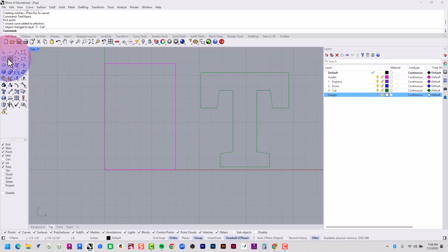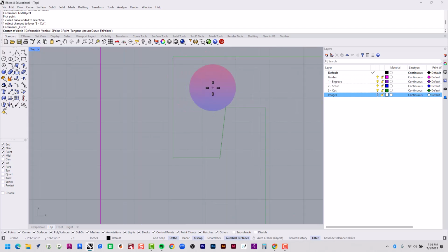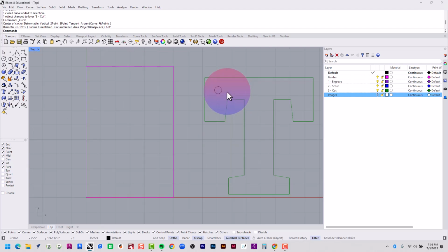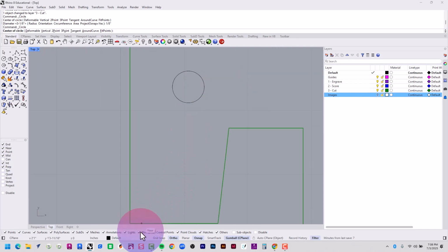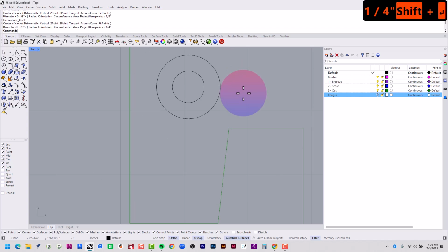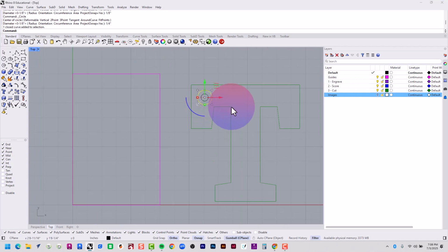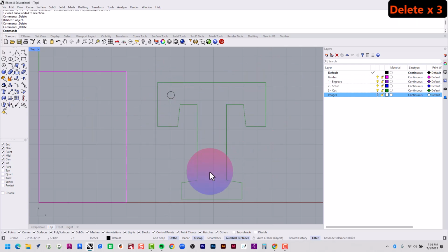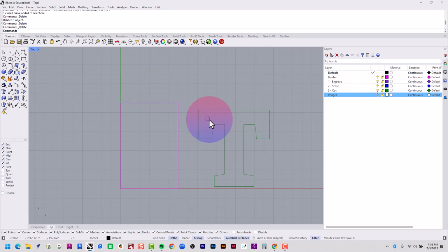The next thing I want to do is figure out the circle. So I'm going to click on the circle command. I'm just going to place the center of the circle somewhere around here. And then I'm going to click outwards, and then I'm going to type in the diameter. The diameter is, let's try 1/8 of an inch, so 1/8 inches, enter, and that's 1/8. If I did that same circle again but at 1/4 of an inch, it's going to look like this, with a diameter of 1/4, and that one represents that 1/4 inch. Okay, so that might be a little too big, might dangle and swing a lot, so let's stick with 1/8 inch. All right, so now I've placed my circle.